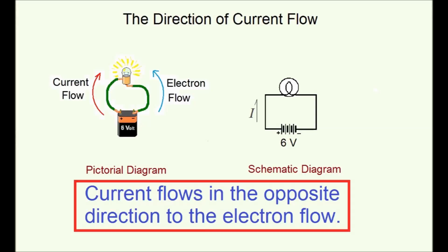The direction of current in a circuit is referred to as its polarity. For many components or devices, the polarity of the applied voltage is not important. For example, incandescent lights will operate in either polarity. Also, resistors or ceramic capacitors have no required polarity. But for components and circuits which do require adherence to the correct polarity, failing to do so will prevent the device from working properly and may result in damage to components or even cause a fire.